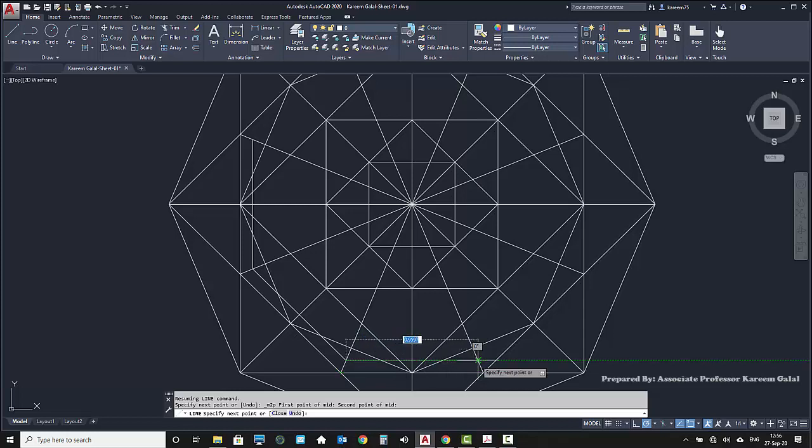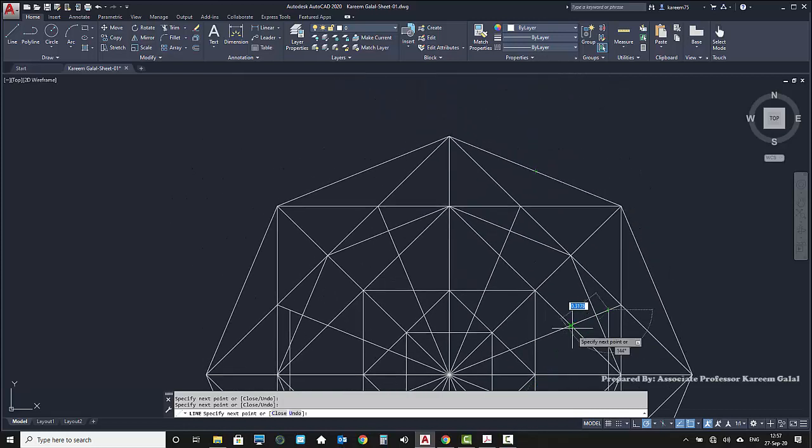We can notice that when we move to the next point there is an intersection OSnap tool appearing. It is a virtual point between the green guideline and the real diagonal line. This tool is activated or deactivated by the Object Snap Tracking tool F11. We can use it to minimize the drawing steps. At the end, type C and press enter to close this polygon.